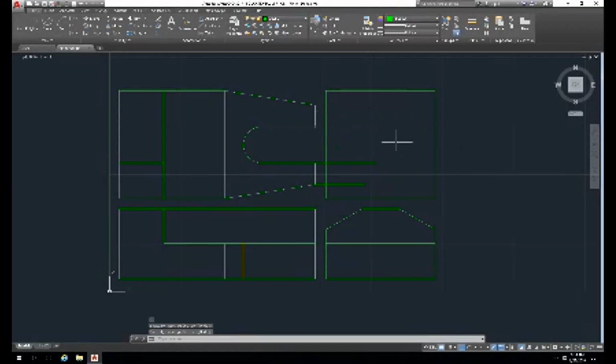There's my third line. See how it shows a square, but when I select INT, it locks on to the intersection line. So here I'm having an intersection only. And this goes down to, well, we have perpendicular, that's fine. Let's do that. But is it gonna touch? Looks like it did. See, here we don't have an end line. Here we have an intersection only.